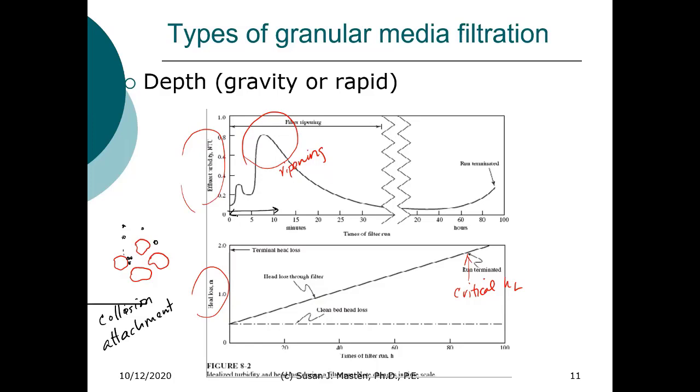there's a certain amount of water that is actually wasted. So that water won't get distributed out to the community because the particulate levels are too high. So that becomes wasted. And then we'd really start maybe here. This is when we would start collecting that water for distribution. And that really depends on the plant. It depends on how well the filters are operating, what length of time you need to waste that initial amount of water that's treated.